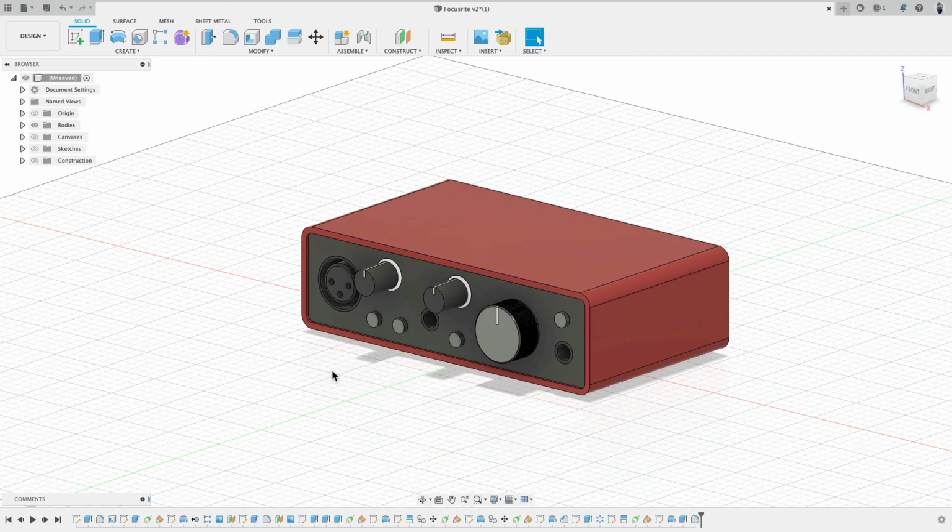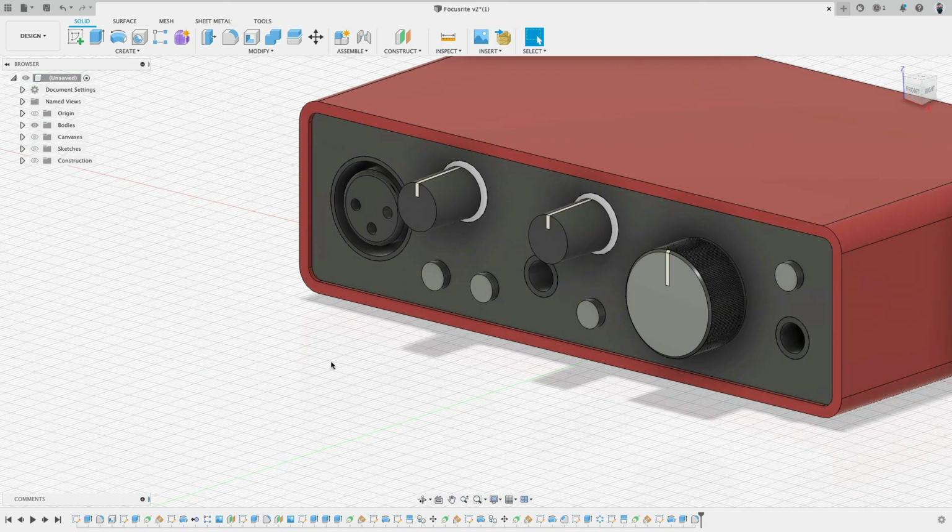If you export this later via OBJ, then each object comes with the material definition, not the material itself, but for example, these dials will have two materials, and then in the render program, for example in Blender, we can modify these materials automatically.